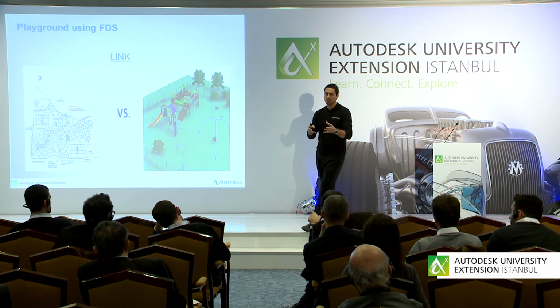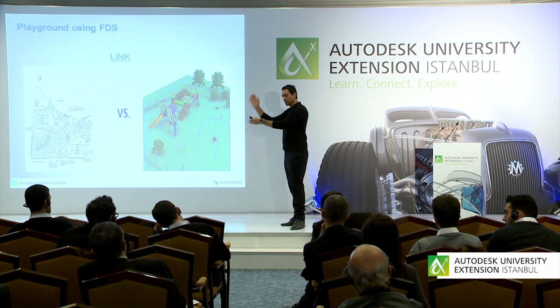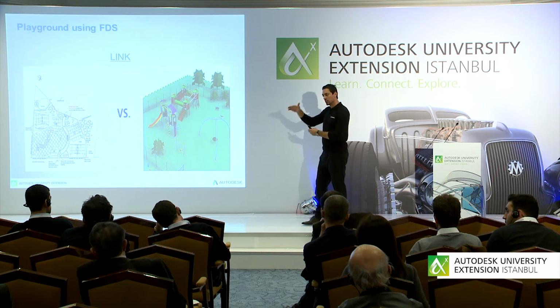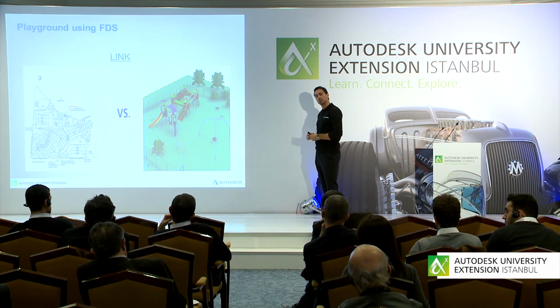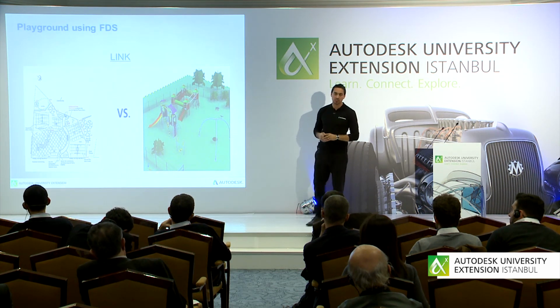So you can build it in Factory, lay out everything, take that into Plant, and run the actual command to give you all the isometrics, the layout, and the lengths of your piping. But it can't be done inside Factory. No.